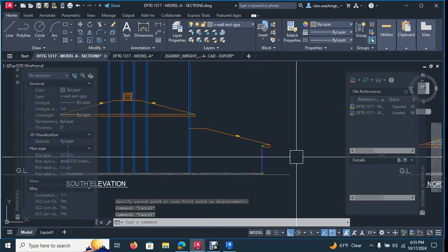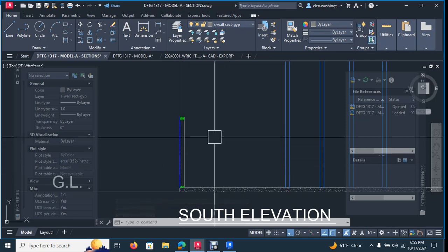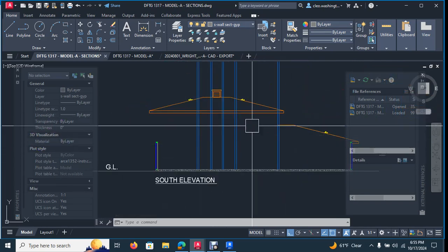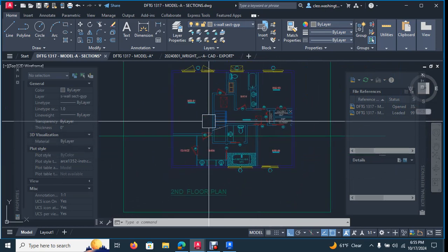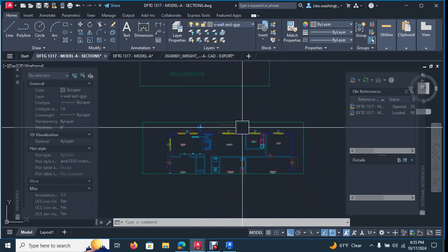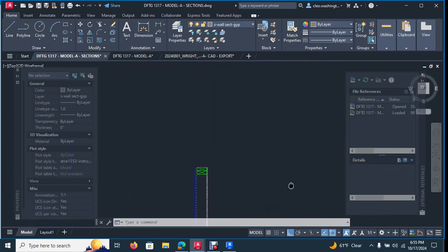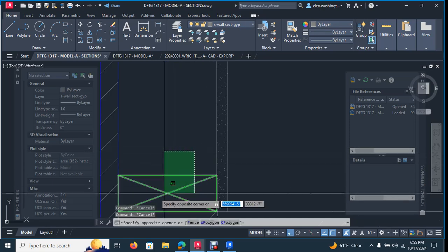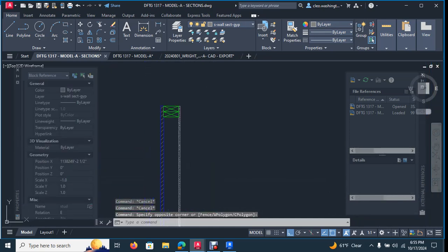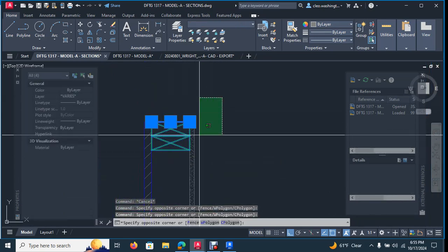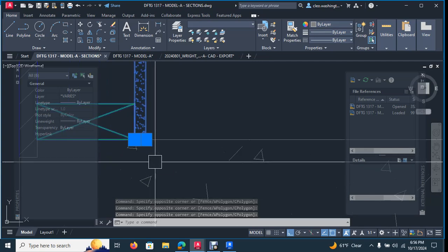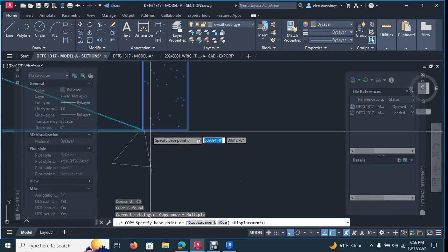Now, these are our two exterior walls. We'll go back and put the window in, okay? Because at this portion, there's gonna be a second story, right? We'll talk about that later. But we'll have a whole deal here for the second story, okay? So now let's take these guys because we have 6-inch walls everywhere, right? You can take this guy and you can take the gypboard because now on the interior walls, you have gypboard on both sides. So let's go ahead and copy this guy over.